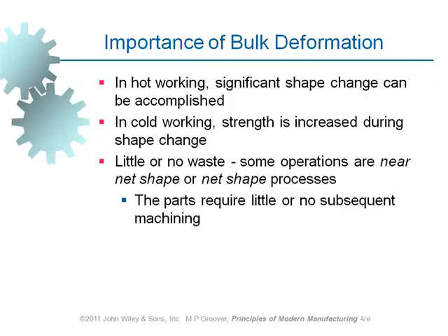However, we know that even if temperature is elevated to a temperature which is above room temperature, it still helps to increase the magnitude of the cold working. And it makes it easier for us to change the shape and geometry of the given material. Still helps. But as new grains are not nucleated and formed, it puts a limit on the magnitude of the cold work which can be applied on the material.